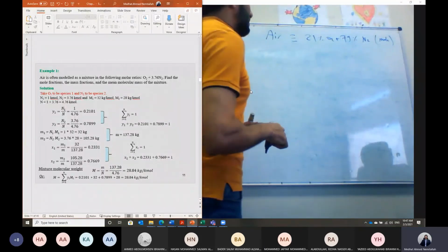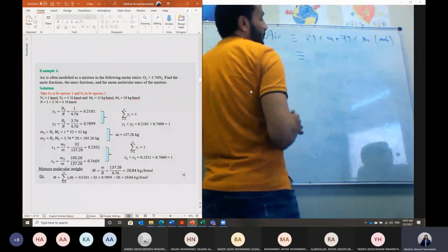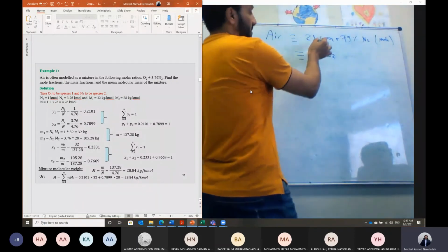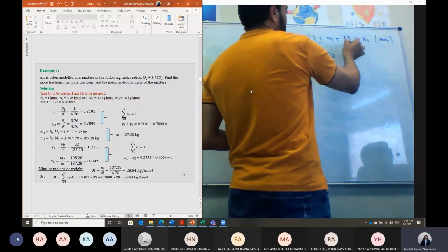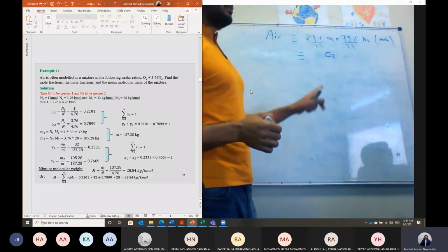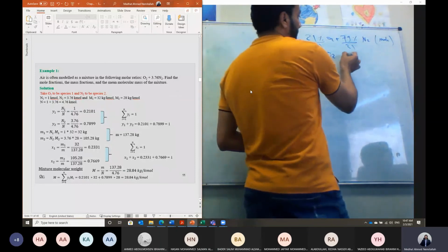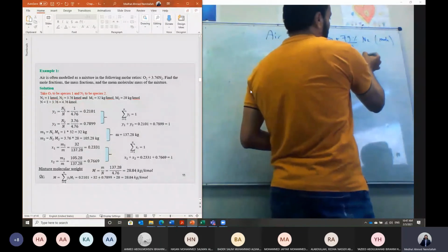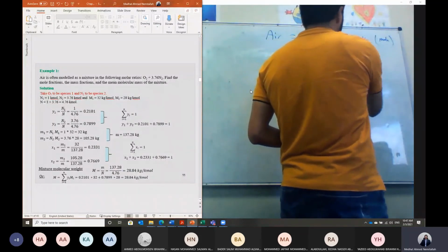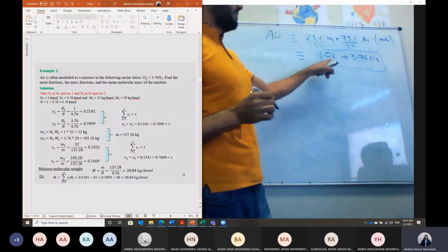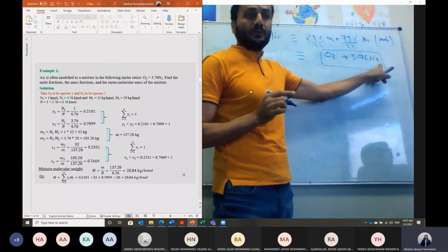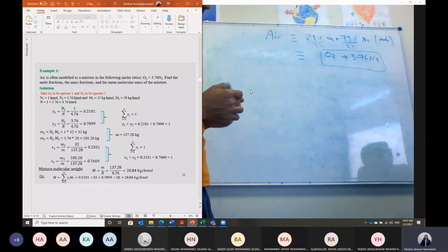So if we have one molecule, we divide by 21, both sides. So each one molecule of O2 will have 79 divided by 21, which is 3.76 N2. So each one molecule of oxygen in the air has 3.76 molecules of nitrogen.